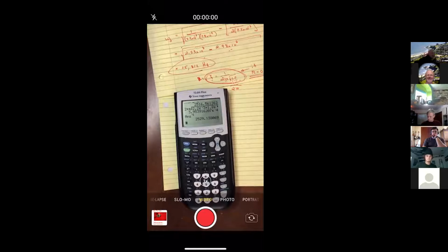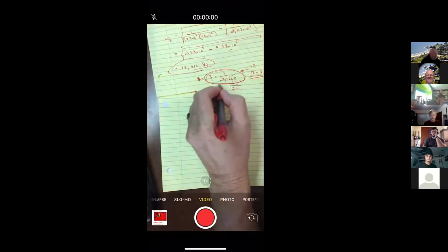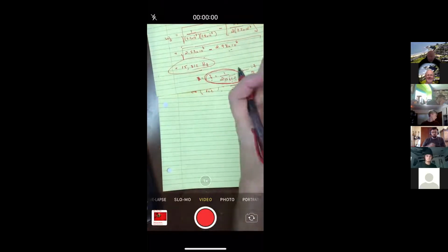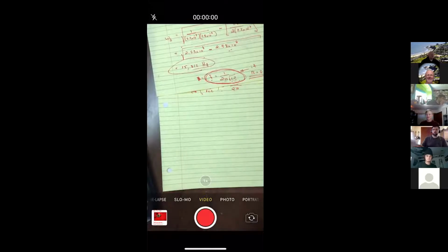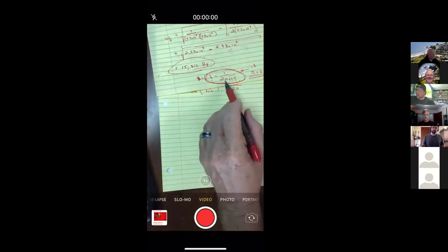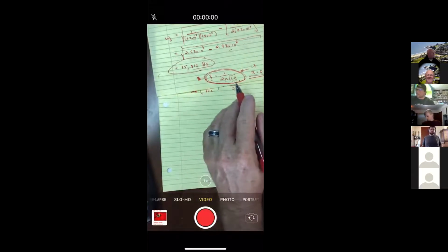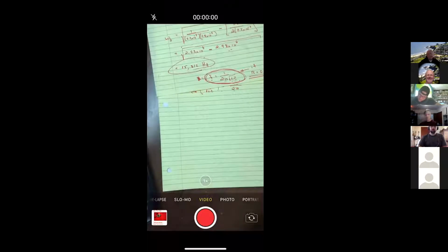But a lot of times, we're only interested in 2 or 3 significant figures anyway. So this equation would be what we might call very reasonable. Completely right, no, but very reasonable. So if, on some of the previous questions, I had just taken what I calculated using the equation they have in the book, which is the square root of 1 over LC, and I just divided it by 2 pi, I would have had the right answer. Oh, okay. I didn't see that. I thought I was using the wrong equation the whole time.